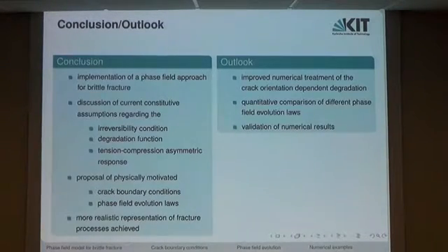To sum up, I showed the implementation of a phase field approach for brittle fracture. I discussed some problems concerning the tension compression asymmetric response, if we treat it in the variationally consistent framework. We proposed some physically motivated models concerning the crack boundary conditions and the phase field evolution laws to achieve better or more realistic results, and there's still much work left. We try to improve the numerical treatment of our proposed models, as well as we will quantitatively compare the different phase field evolution laws and validate them.